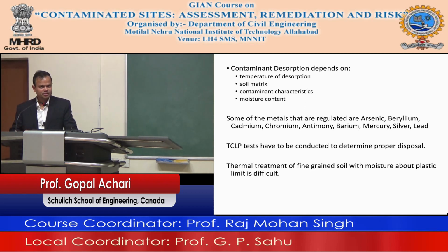Okay, are you with me on those steps here? You need to make sure that your treated gas, whatever comes out of the cyclone at the top, is clean. You know how a cyclone works, right? You take that gas and send it through a cyclone, the solid particles fall to the bottom, and the gas goes to the top. The dust particles still need to be collected. You add water to clean it, to cool it down, and then dispose of the clean solids. That's the basic mechanism of it.